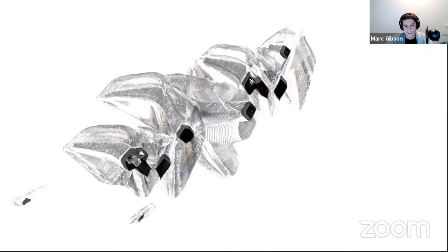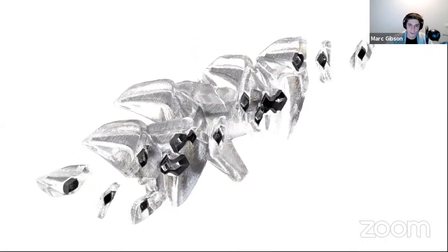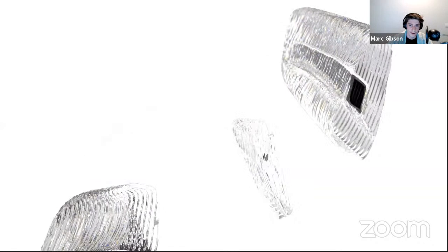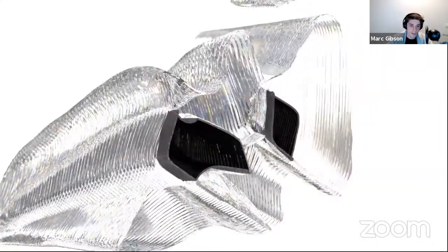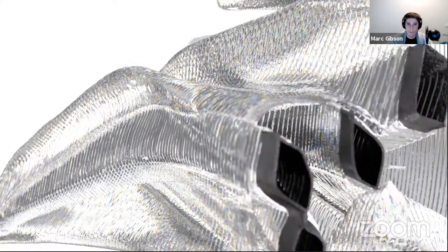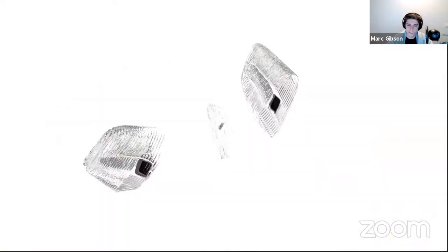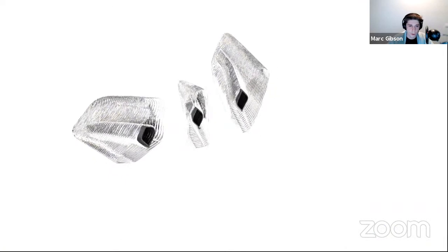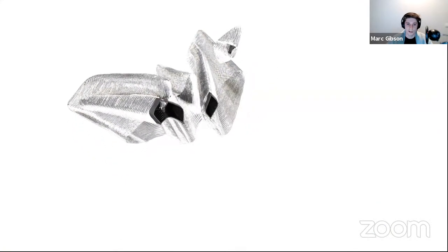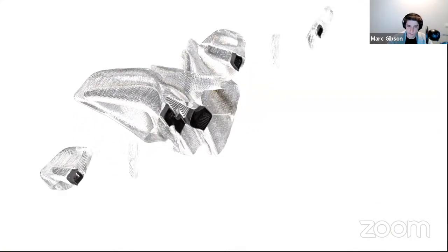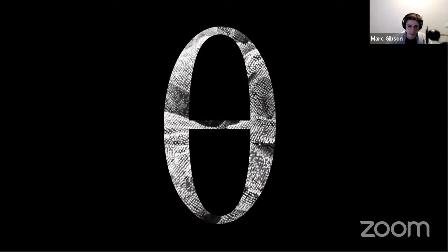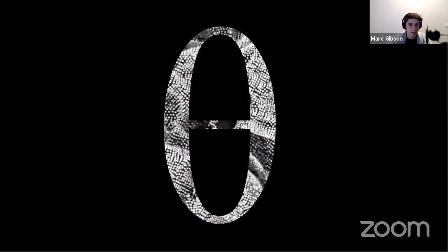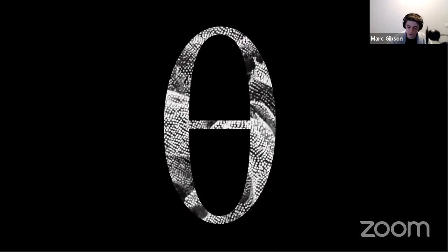This is further exacerbated in our projects because we're dealing with not only highly detailed forms in terms of the mesh size, but the variance of the shapes themselves. These generally require multiple cut planes and offer up further challenges. So as part of this, I developed a piece of software which could help essentially run multiple draft angle analysis.